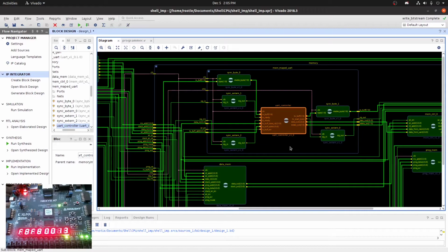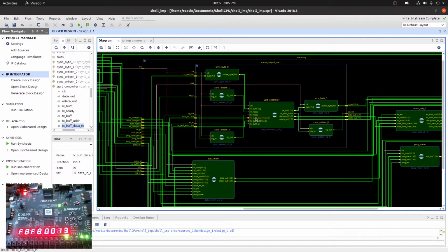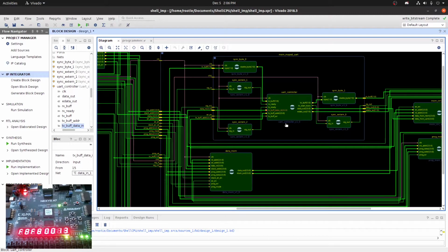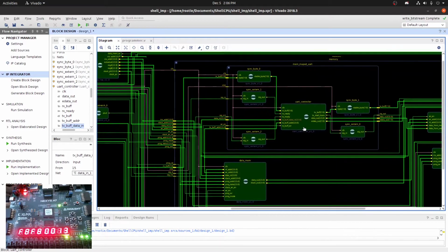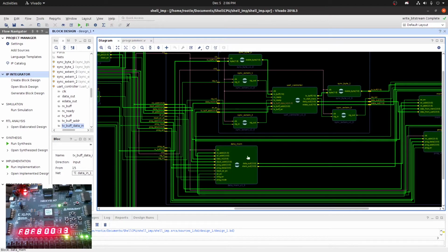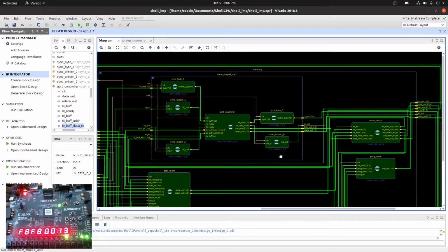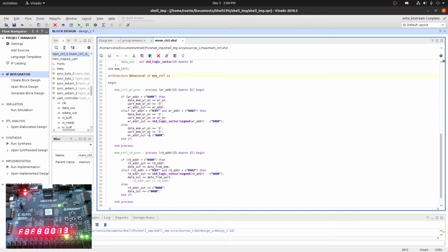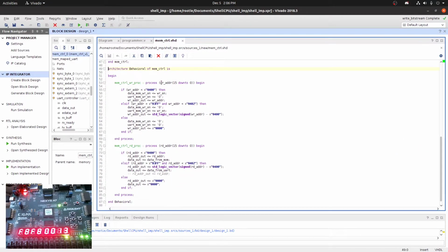And then I've got a UART controller in here, and this has a few registers that the CPU can write to. But for the address space, it would be kind of confusing if everything had its own address from a hardware perspective, I guess. So I made this memory controller that, when you write to certain addresses, takes that address. Let's say the UART controller is at hex 400. So if I'm going to write to 400